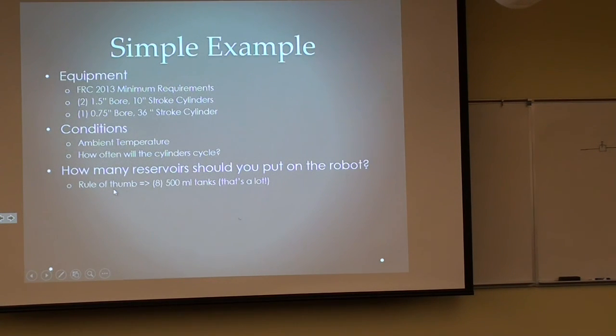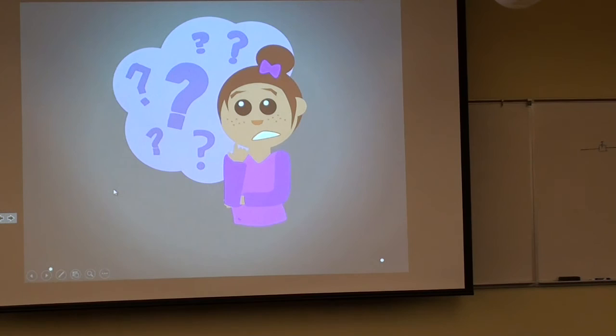So, my best advice for this is test it. Make a good educated guess on what you think you need, based on the size of your cylinders and how often you're in a cycle, and then test it. Because you're not going to know for sure until you test it. Okay, any other questions? I ran over on this one.